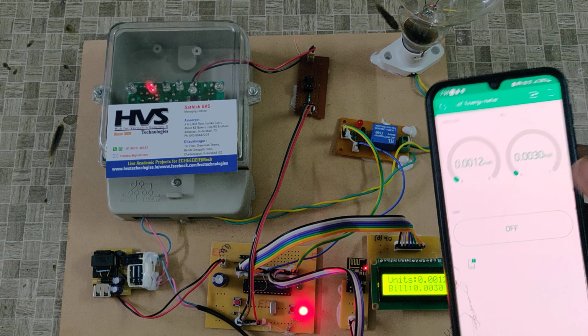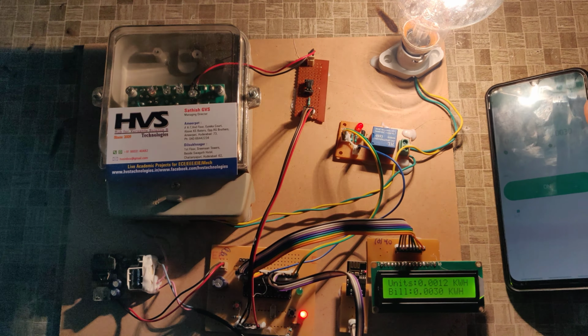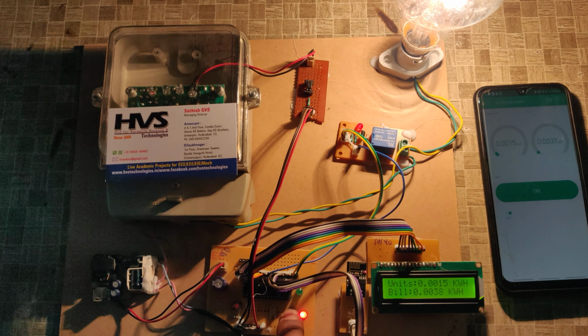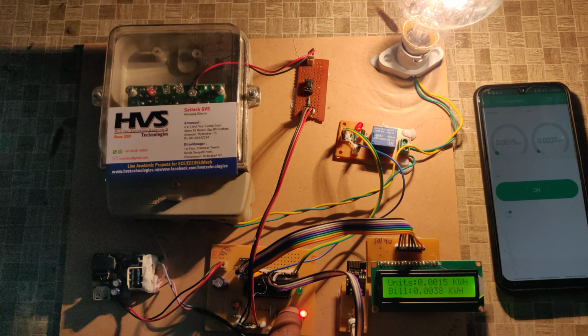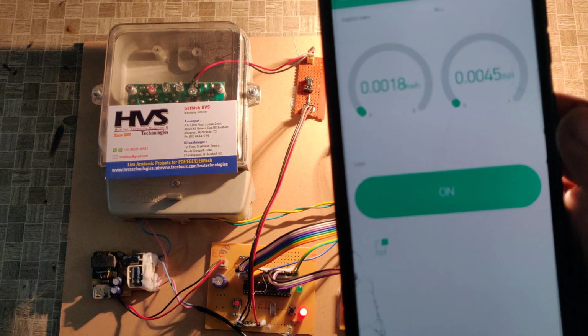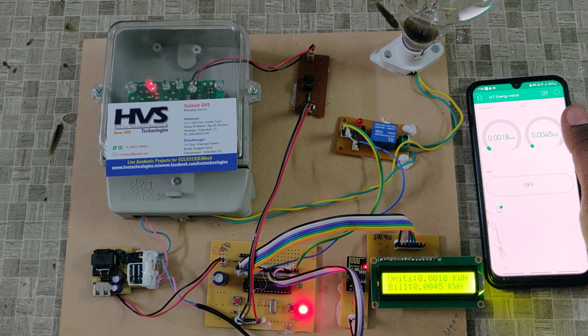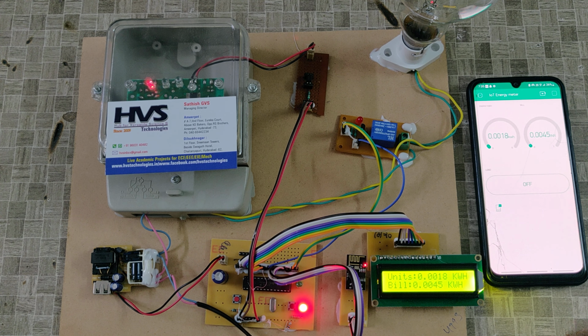If the kit doesn't respond to your Blynk application inputs, you can just restart the microcontroller. There is also a fault switch. When a fault occurs, we get an app notification alert saying there is a fault. We can see that, and you can isolate the power supply to the load. Right.